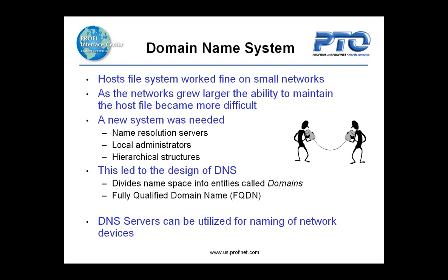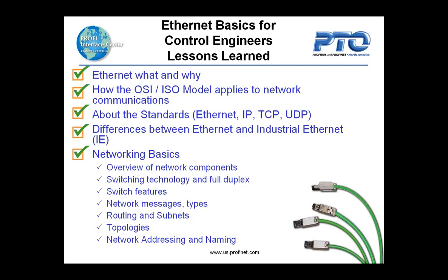And now we can, again, take advantage of that naming concept, and we can use naming with our devices. If your factory network allows you to do that, you can have all of your devices named, and then you can put those in the list on the server, and you could then access the device by its device name even. And that's known as a DNS server. And with those devices, we would use, for instance, a fully qualified domain name is what it's called, or an FQDN.